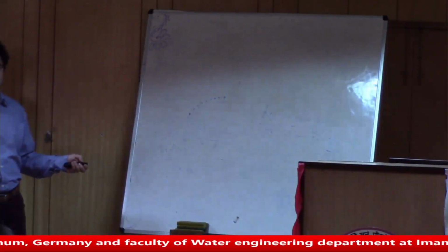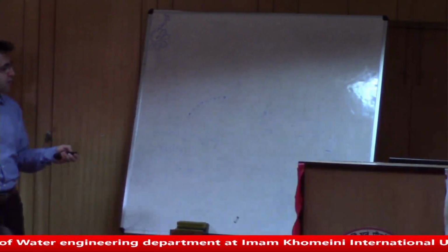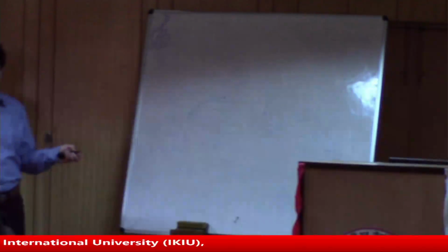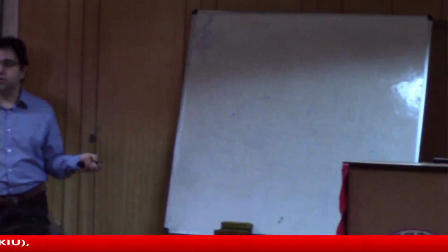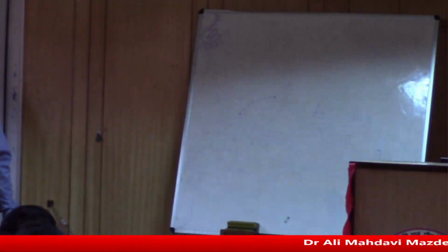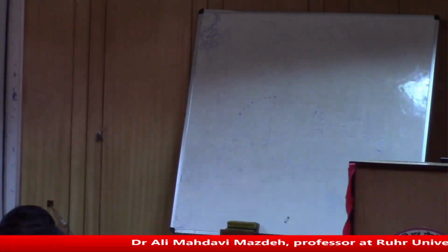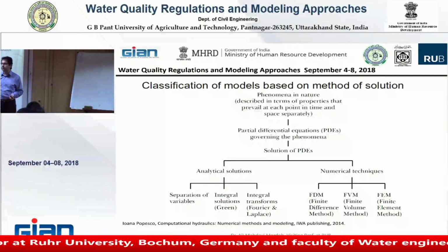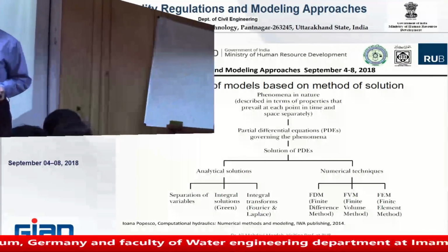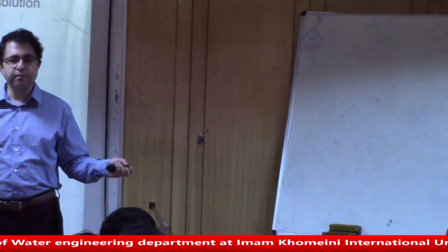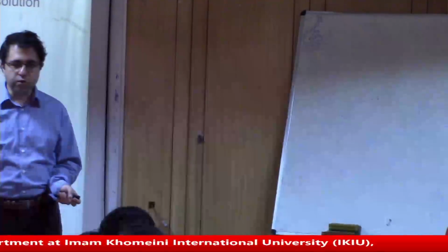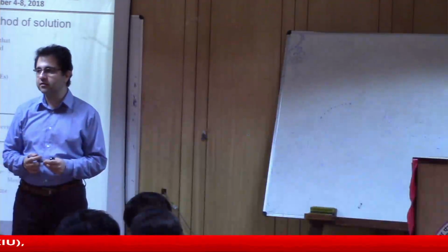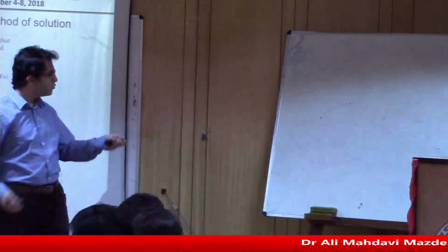Yes, you should solve this equation. And for this, you must make an integral from this. Then you will have y as a function of x. If you can make an analytical integral from this, then you will have y as a function of x. Then you solve the problem, and you can exactly say how the water profile behind the gate is. How many of you know this equation?